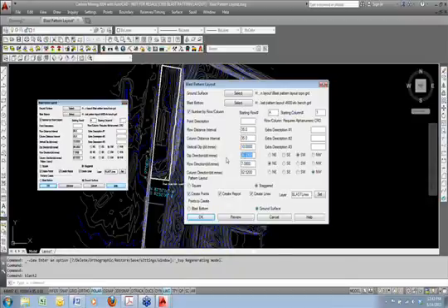The dip direction, now this is important: you must put the number in between the letters. So I'm going to match this window over here. I'm going south 96 degrees west for the dip of those. That's the dip of the hole at 10 degrees. The row direction, starting here at my first hole, I want to go up to the northeast, so that's north 7 degrees east. The column direction, and this is why I labeled the bearing beforehand, is going to be north 82 degrees west, going that way.